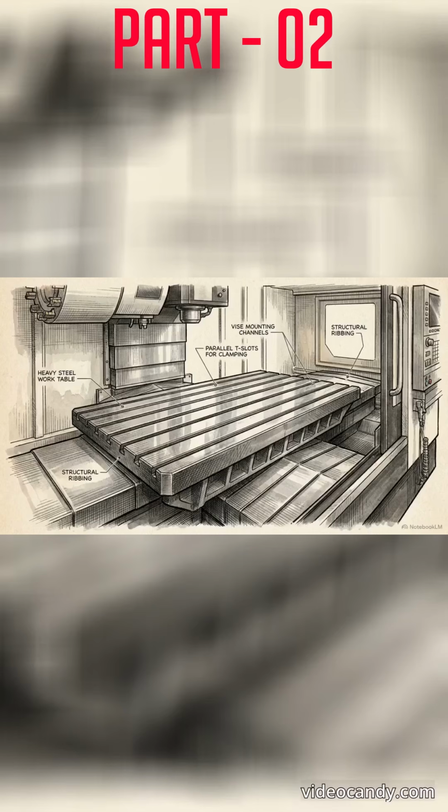Internal specialized geometry requires specialized tools, like the T-slot cutter. Mounted on a straight or taper shank, the T-slot cutter features profile-sharpened, staggered side teeth. As it moves through a pre-milled channel, these teeth carve out the wide base of the inverted T-shape.